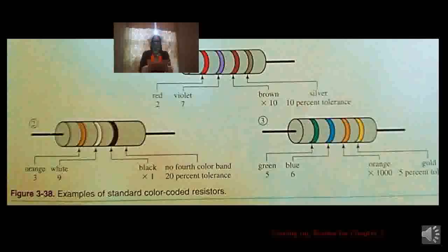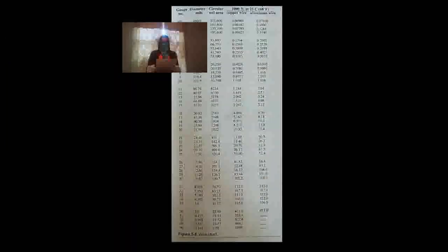Film technology is not restricted to single resistors, but may also be designed to produce resistor networks on a single chip. A resistor network consists of 2 or more independent resistors contained in one single surface-mounted package.